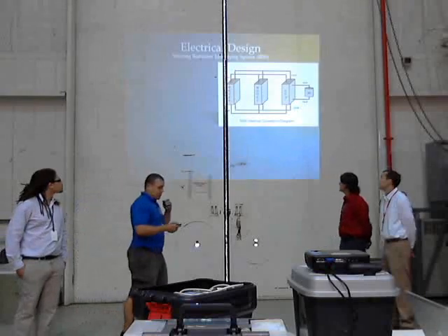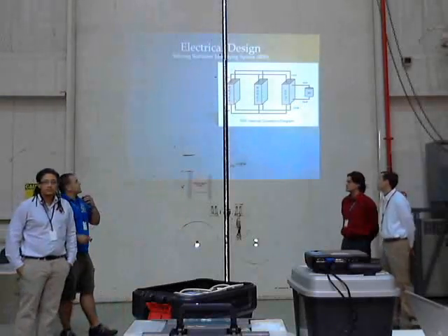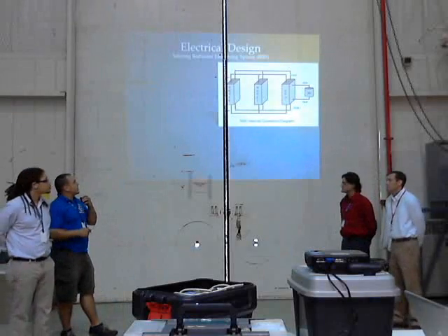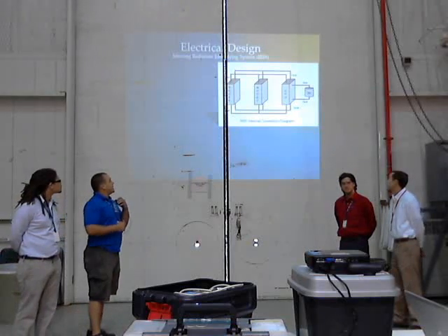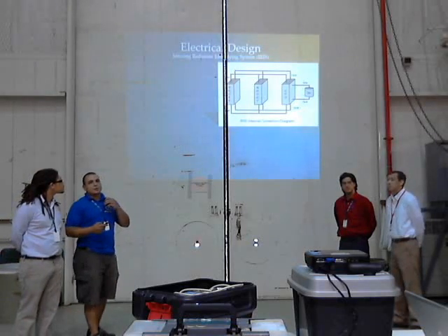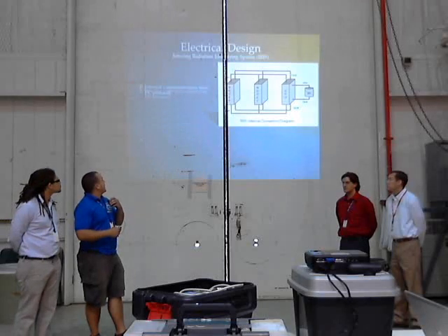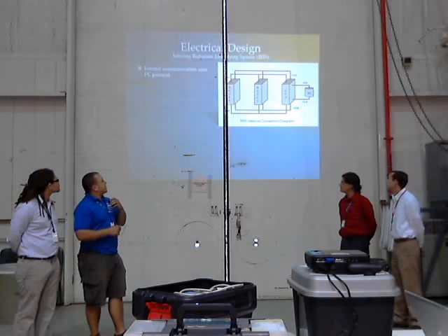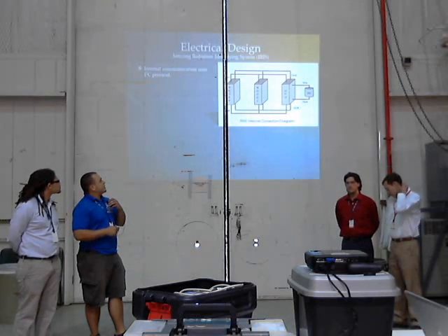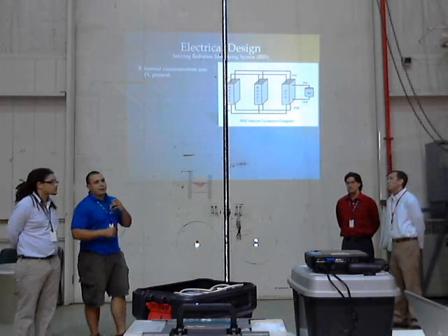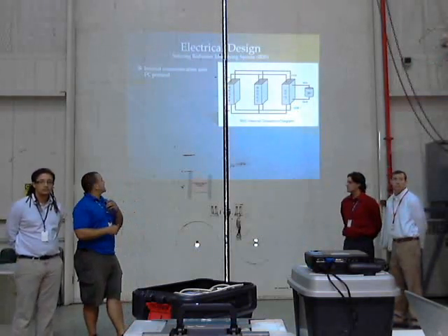All right, for the ionizing radiation portion, for the IRIS, we have a system diagram showing the main 3 functional groups of the system, in which case it's divided up into a CPU, or centralized processing unit, NRD07 and NRD60, which are just names that I came up with for shorthand. Now the whole system is going to communicate using an I2C protocol. As you can see, the CPU hooks directly to a lithium-ion 9-volt battery, and it distributes power to the other sensors in the system.